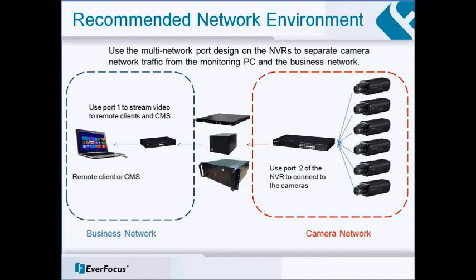EverFocus recommends separating the camera network from the business network. Use the multi-network port design on the NVRs to separate camera network traffic from the monitoring PC and the business network. The Elite and Commander NVR each supports 2 network ports, and the ENVS provides 3 network connections to further divide the heavy camera traffic. For assistance in designing a robust network infrastructure, feel free to contact an EverFocus systems integration specialist.